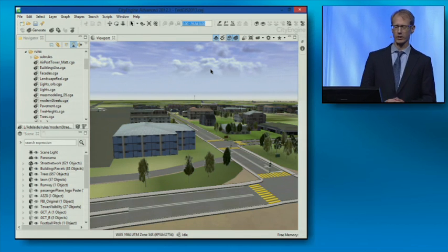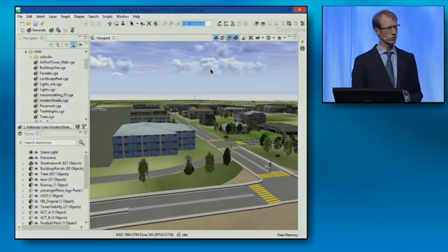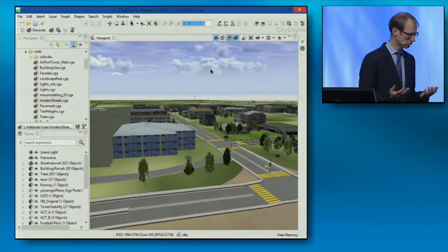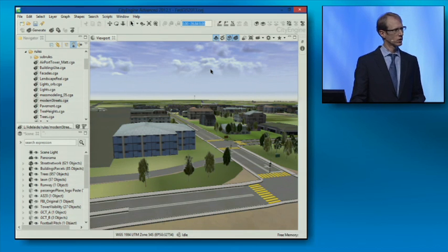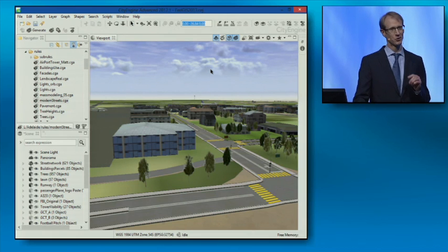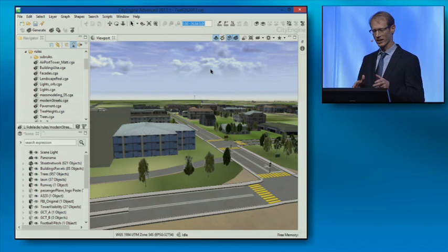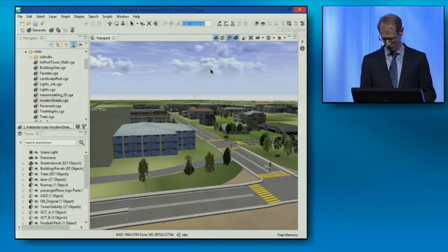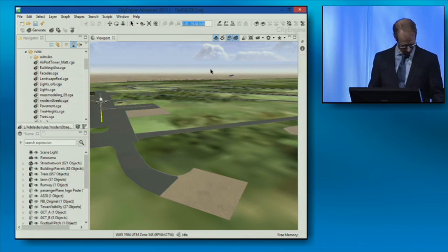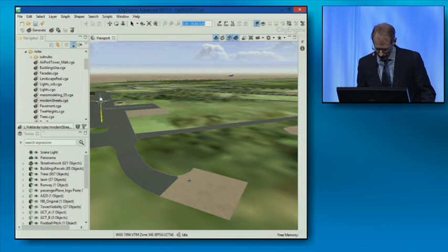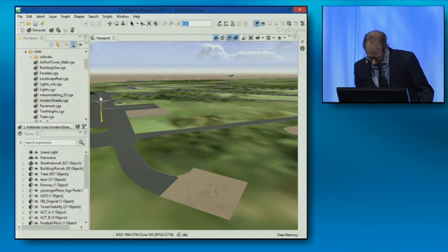Now, for that new tower I mentioned, there's quite a few ways you can create new content. You can import your CAD drawings from your contractors, maybe use Collada models, or any of the other dozens of industry standards for 3D data. Or you can design that directly here in CityEngine using our new editing tools. So let's zoom in on our proposal area and see what I can come up with. We'll start by sketching out our foundation for our building.